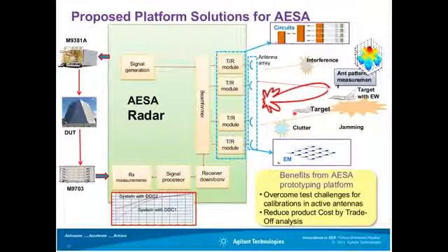Not only that, we allow the user to link this simulation data to Agilent hardware to generate the test data for multi-channel testing of the antenna array system, and the signal received from the antenna can be captured by an Agilent multi-channel digitizer and linked back to the system to do further signal analysis to find out the RX performance.